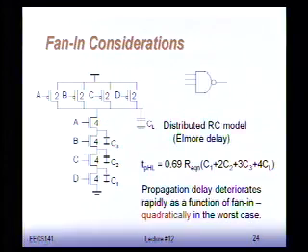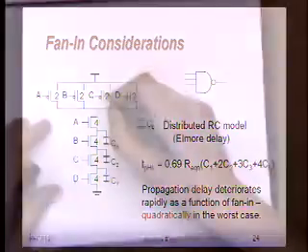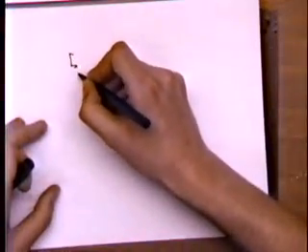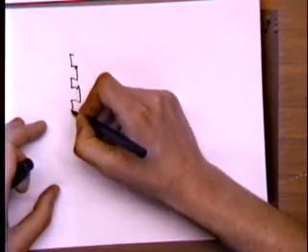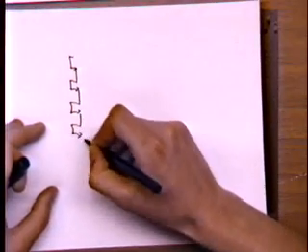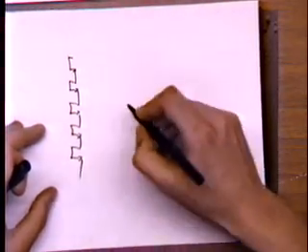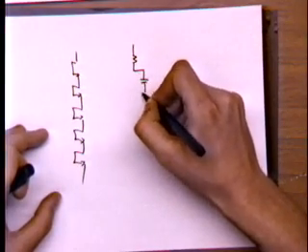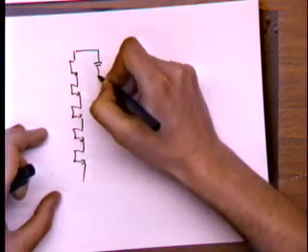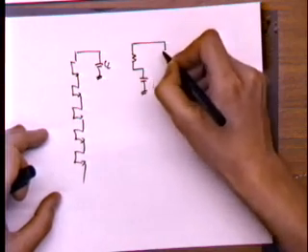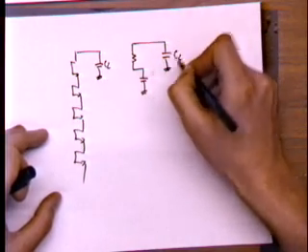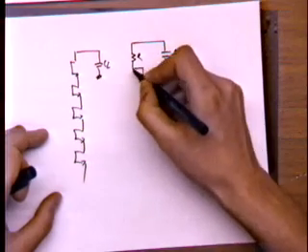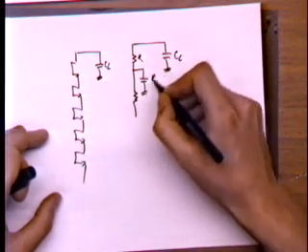In particular, what you can do is the following. Let's go to overhead now. If I give you this long chain of transistors, you can replace each of them with its RC model. So there is CL here, right? The first transistor gives me an R and a C. Then I go into the second transistor.